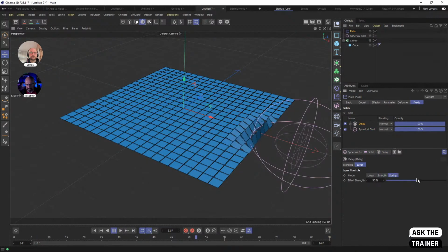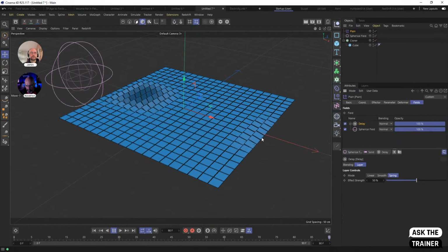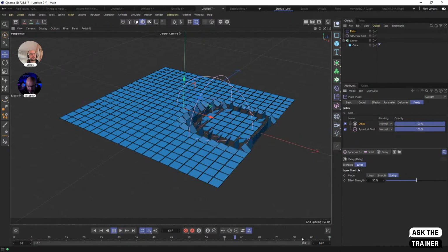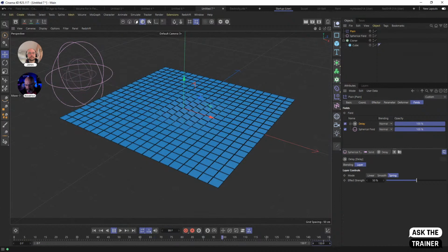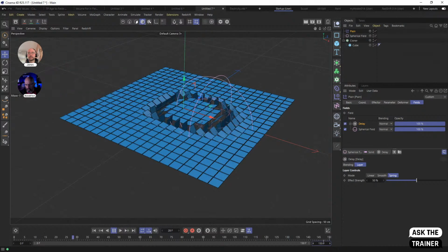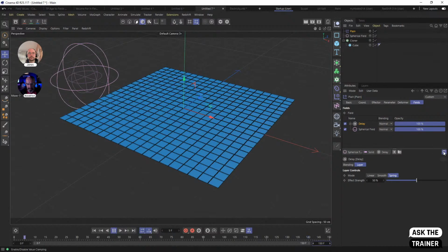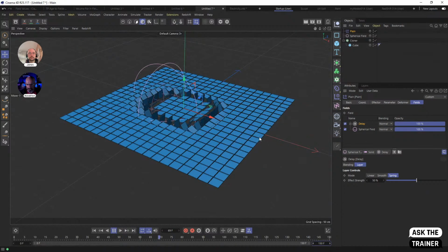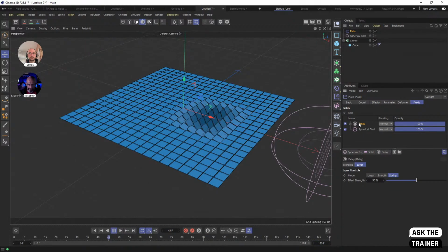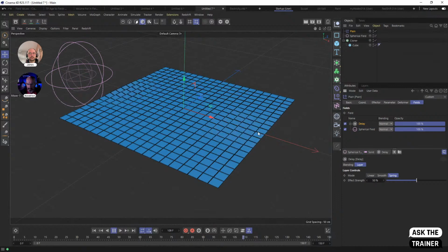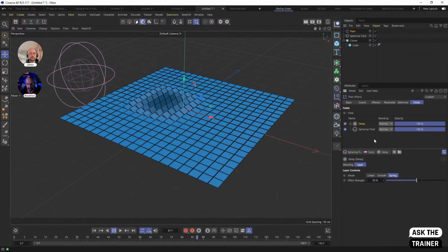Now what you're observing here is that they only do half of the rotation when they, let me put this at 150. So we have a bit of delay. Look at that. They're not flipping 180 degrees. They're flipping halfway through. This is a product of the clamp. Because these cannot go in negative rotations, and the springiness when they're recoiling back wants them to go, but the value is not there. The value gets clamped at 0 degrees. So if I unclamp this, now you'll see them rotating.